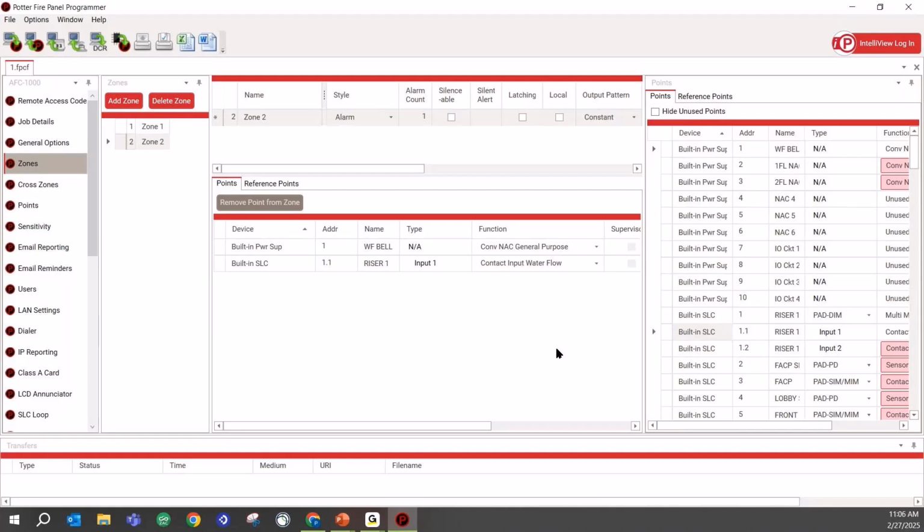Number 3, quite often in line with that riser, we have an FDC. And if they're going to leave the sprinkler system running, there's a very good chance that there's not going to be enough pressure to charge hoses off of that FDC. So if that bell is sounding, they probably want to put a variable pressure pump in line with that FDC in their hoses. So I'm going to say, for this example, non-silenceable and non-latching.